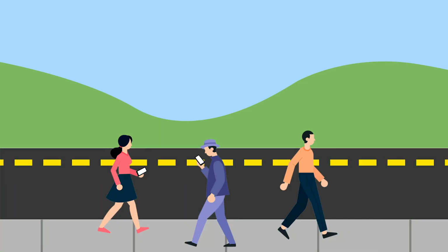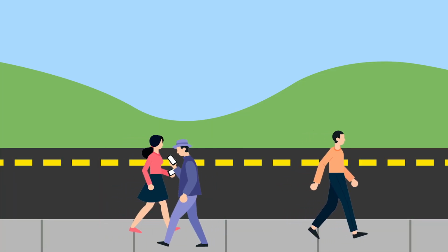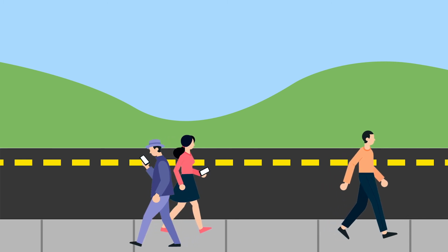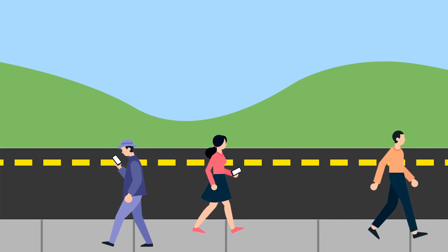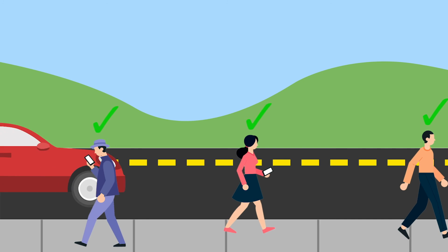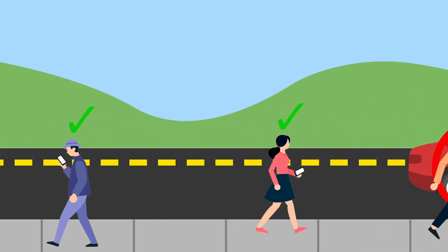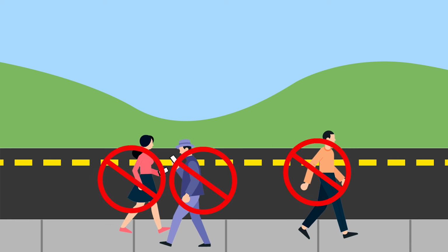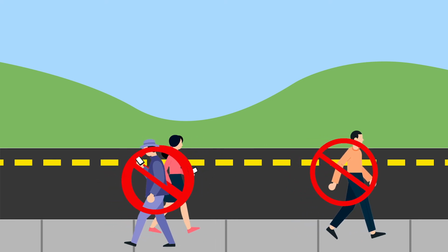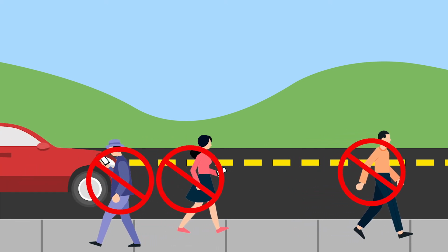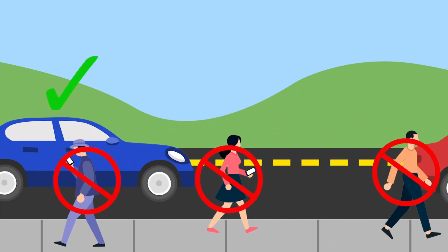An interesting usage for filtering is if you wanted to use the sensor as a people counter, you can set the maximum speed so that the sensor does not pick up objects moving faster than a person would, such as a car passing by. Similarly, you can set a minimum speed to filter out people walking if your aim is to track cars on the street instead.